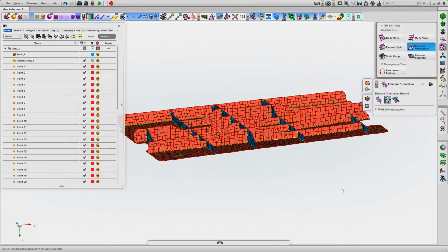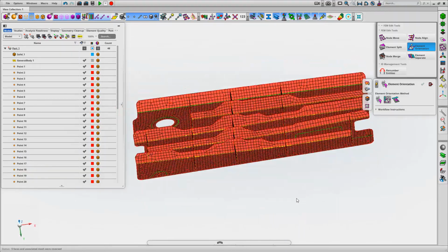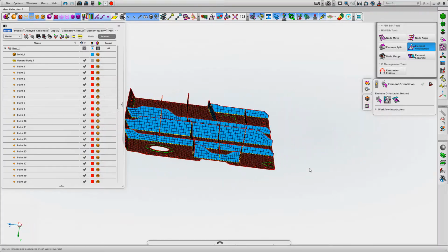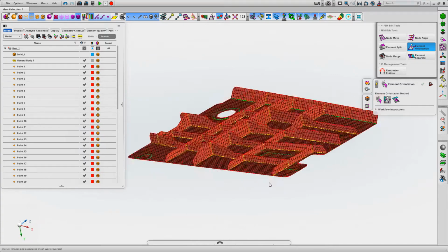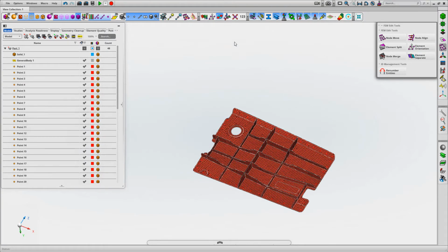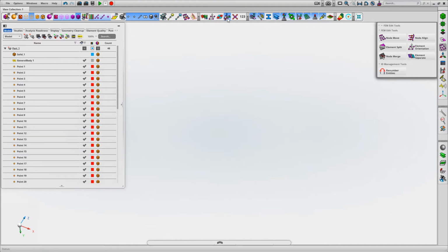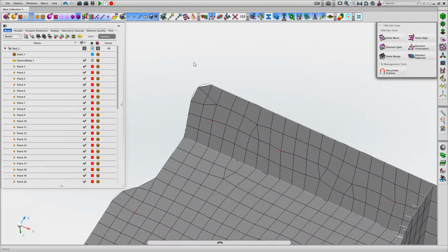There we are. Okay, so all the stiffeners in that plane are going one way, and all the stiffeners in that plane are going another way, or the consistent way. Okay, so happy with that. So once we've got the normal consistency defined, we can look at the normal directions. Actually, excuse me, that wasn't the normal direction. Here we are, shell normal vector.